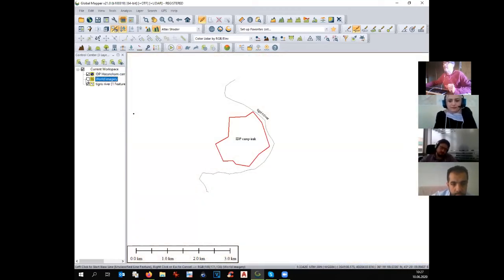The river is there, and I have to put the elevation on that river so that I can simulate what happens when I increase the water level. But this is a line, and the software is not able to give the elevation to a line, because it asks you only for the starting elevation and the end elevation, and for the software the line is straight. So in that case I have to convert the line into a shape, and it's easy to do that.